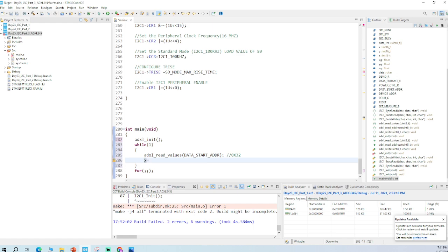So I'll write one and copy this. X of data receive of 1, receive of the first, shifted 8 times, and then simply OR this with data receive of 0, data receive of 0, and this is X. So likewise you need to do it for Y and Z.